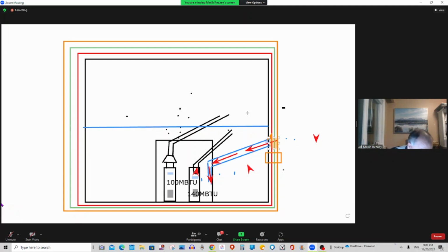By which clause number? Clause number 8.2.2. I add them: 100 plus 140 is 240. I go to 250. For 250, 18 and 5. So 18 and 5, and 14 and 4. Which one is bigger? 18 and 5 is the answer: 18 inch square, 5 inch round.